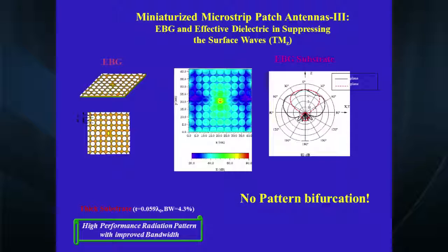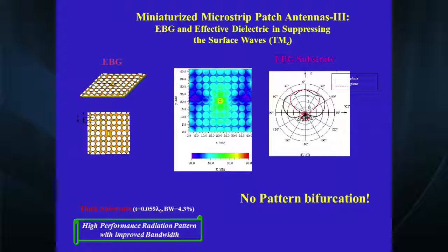So one of the areas where you can use this metamaterial is to put them on these band gap structures, which are now holes properly created in this material in order to prevent propagation of surface waves. And it enhances your bandwidth and also overcomes that bifurcation. This is just an example of how this metamaterial may potentially be used to synthesize characteristics of some more miniaturized antennas. So if I jump over this one, then we are done.